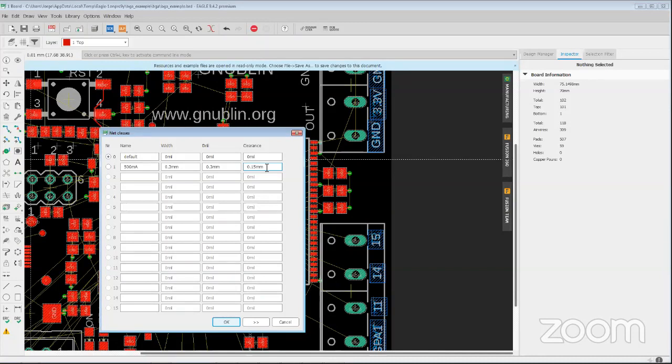Okay. So don't, because we've had some instances where they'll call the class ground, assuming that it will automatically connect to all your grounds, and that's not what's going to happen. Yeah. So it's best to create a class called power, and then you could assign that to your grounds and VCCs, VDDs, and everything else. So you just create the class and then assign it. Okay.